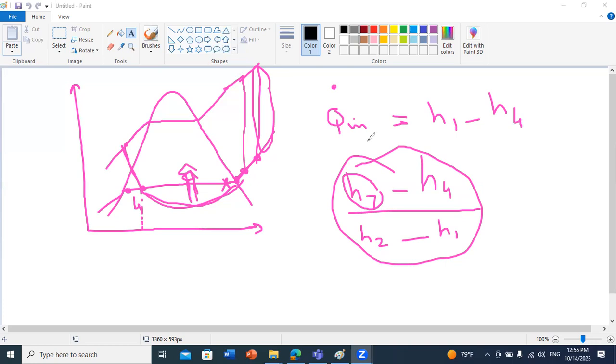I might just tell you, for example, describe the cycle, why we use it, how we can enhance its efficiency. Or I can give you a problem on refrigeration, on Rankine, or any of the applications we tackled together. You should understand how the cycle operates and how to calculate the enthalpy at different points.